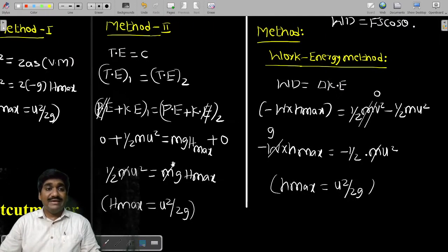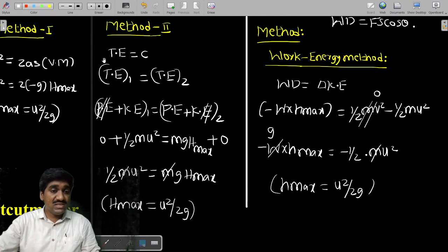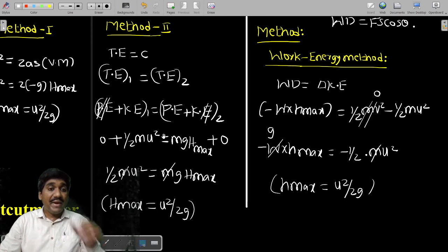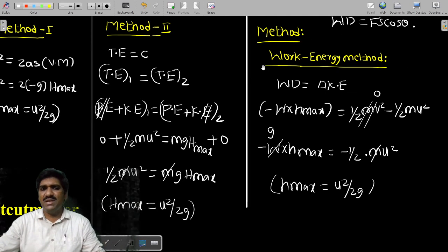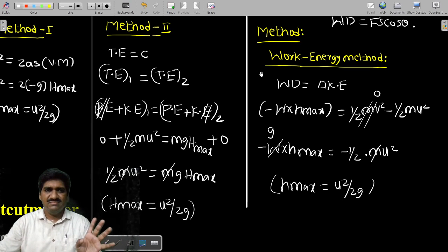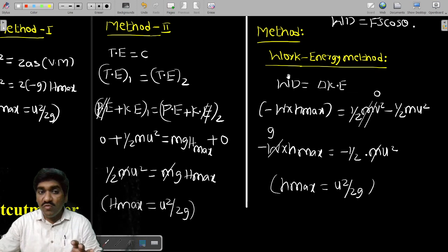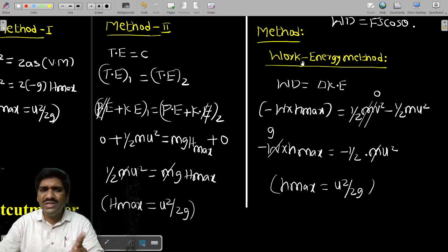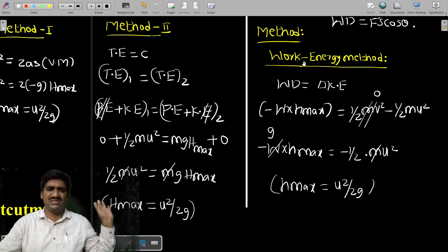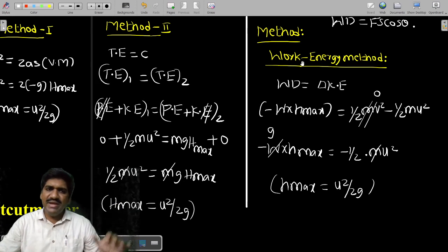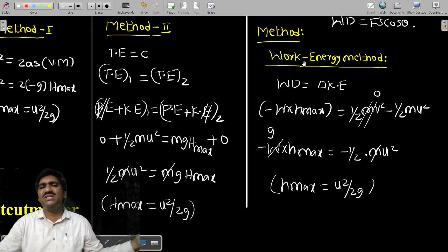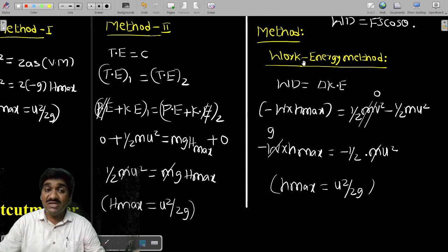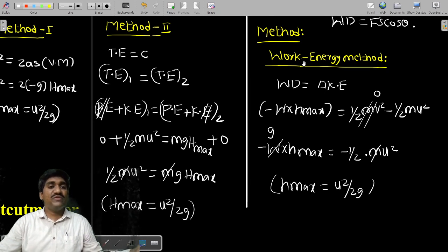So my dear students, sometimes conservation of energy is there. Conservation of energy might be an alternative method for the work energy principle, but not always. I want to say one point clearly: if you go for the work energy method, you have to know the work done by all the forces, by internal forces, external forces, everything. But if you go for conservation of energy, no need to go for all those things.